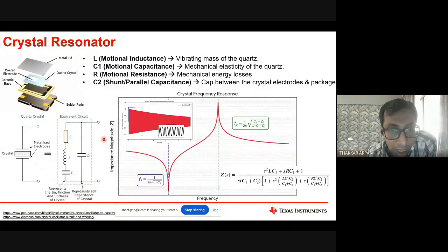But that less than minus R has to become exactly equal to R, then only the amplitude will be stable. And that is an autonomous process inside the cross couple pair. Its GM will start reducing because the device swings are larger across it, the devices themselves will go into triode region and start reducing the gain of the cross couple pair.